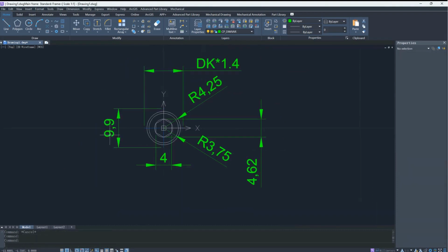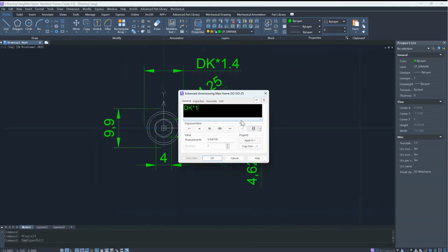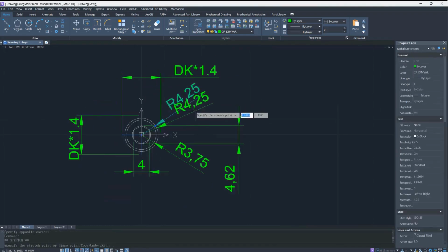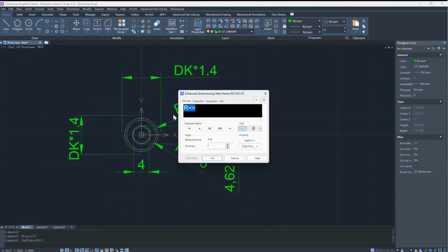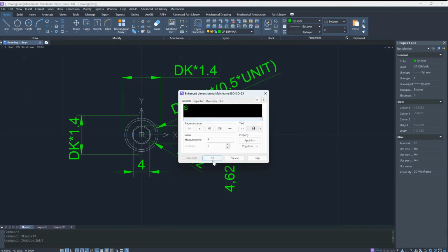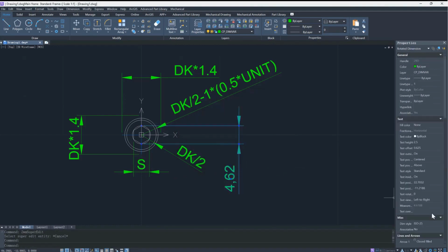When entering constant numbers, we need to enter the unit after the constant number, so that the constant dimension will be scaled to the current unit. For the diameter of the smallest circle, we can use the geometric relationship of trigonometric functions to connect it with the known variable s. So the diameter of the smallest circle is equal to 2*s*tan30, and should be written as 2*s*tan(30).